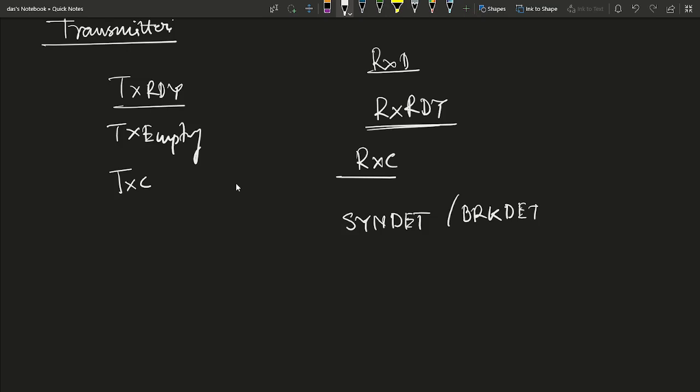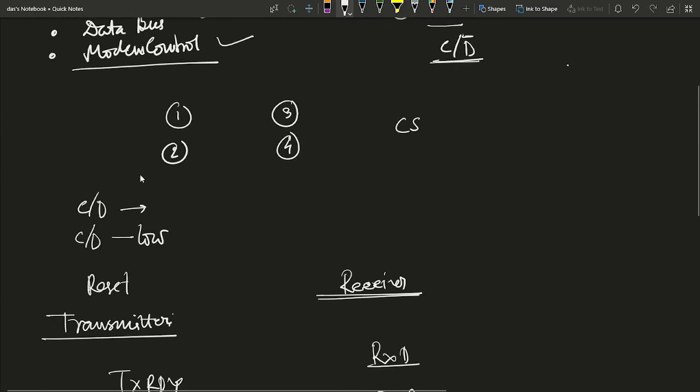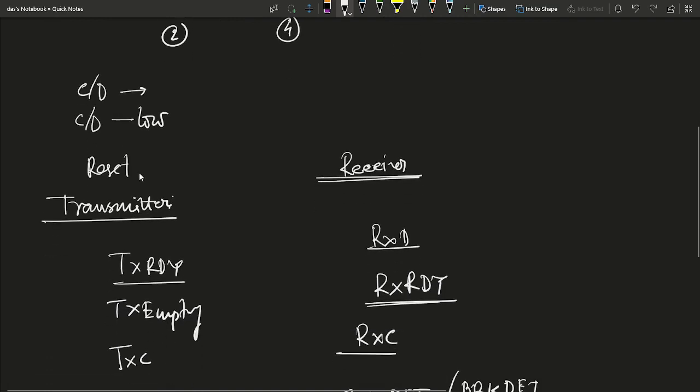Now we discuss the data bus and modem control. The modem control unit allows interfacing a modem to the 8251, and establishing data communication through the modem over a telephone line. The 8251 is IO mapped in the system, as shown in the following figure. One thing should be remembered: until the 8251 gets the handshake signal from the modem interface, it cannot communicate any further characters.